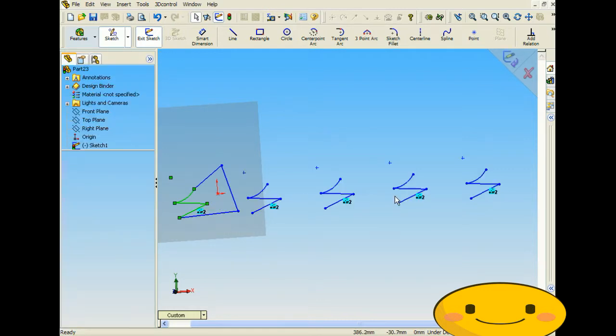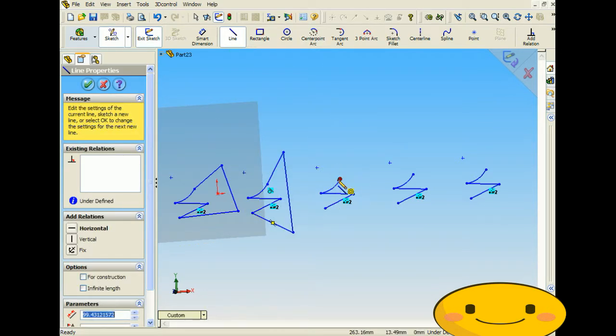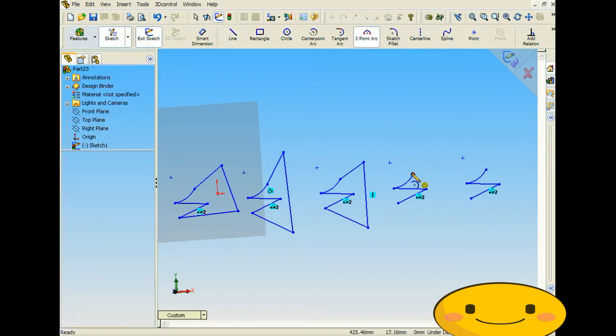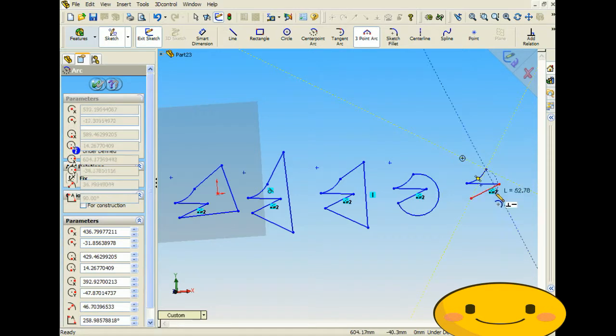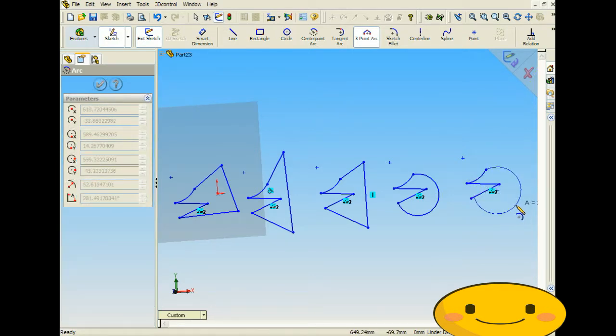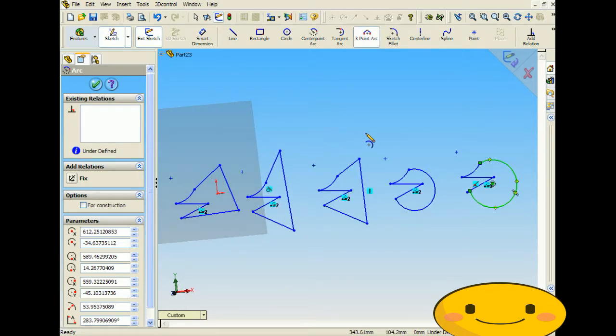So click OK. And why you would maybe want to do this is that if each of them are going to be specific and different. So you have the same kind of opening there, but each one is going to have a different kind of backing, but they still contain the same basic opening. So that's another way you might want to pattern. Alright, and that concludes our tutorial on how to use the linear pattern sketch feature within Solidworks.